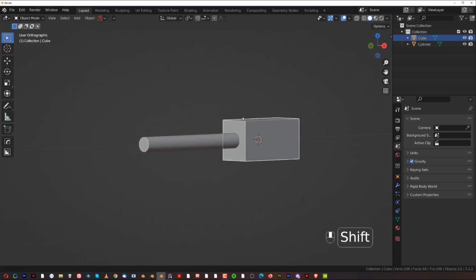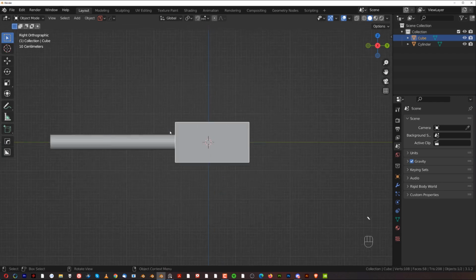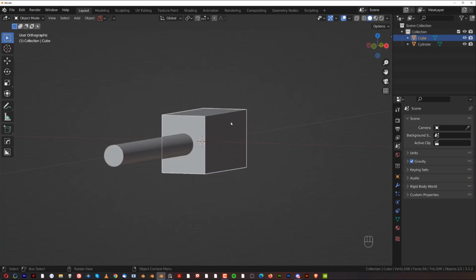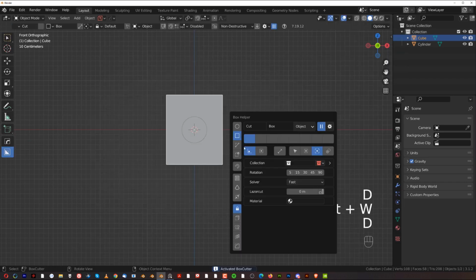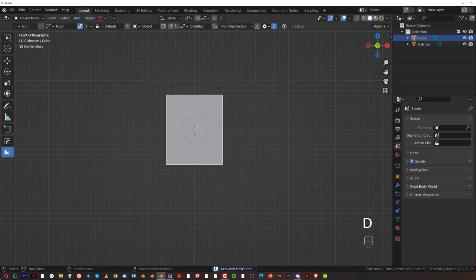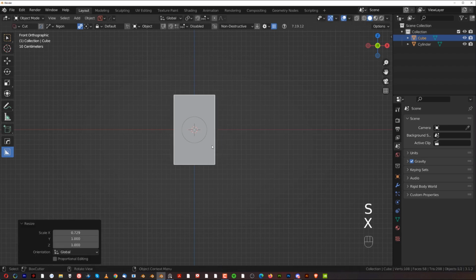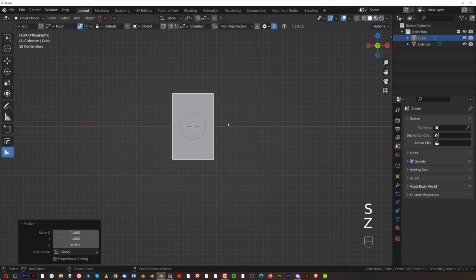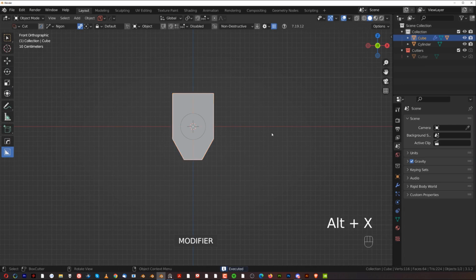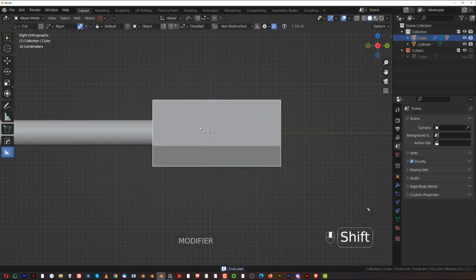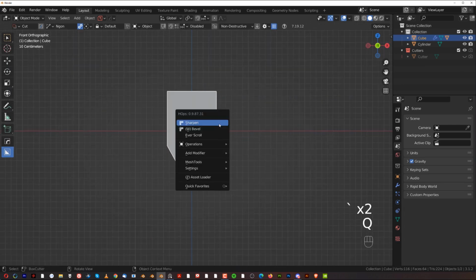And this is a very basic blockout. And then once you do have that, you start shaping things up. So we could grab Box Cutter and Angle and start actually chiseling this away. We can make this a bit more narrow and a bit less tall and start cutting this here. So we could cut it like this, and we could mirror this to the other side with Hardops. And maybe we could actually move it a little bit higher.